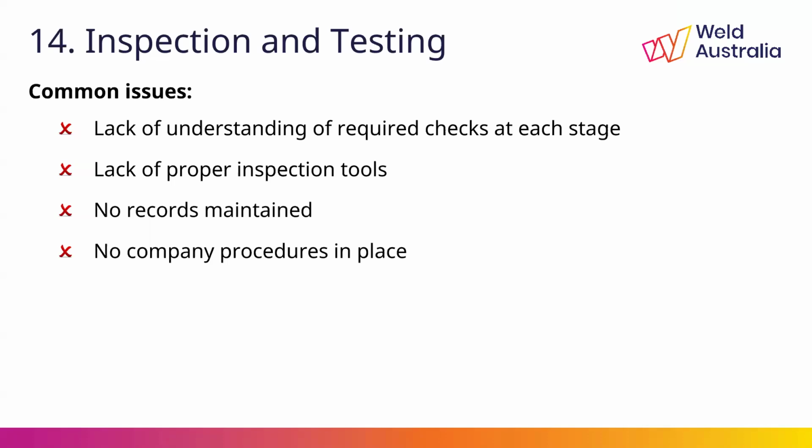Thank you. So another question. What is the competency of personnel for signing inspection reports? Yeah, the competency of the personnel for inspection report, if that's a visual inspection, as I said, the inspector doesn't need to have a specific qualification. But if it comes to NDT, like PT, MT, UT, or RT, the minimum requirement is level 2 ISO 9712. And this is the standard that is referenced in part 5 of the standard.